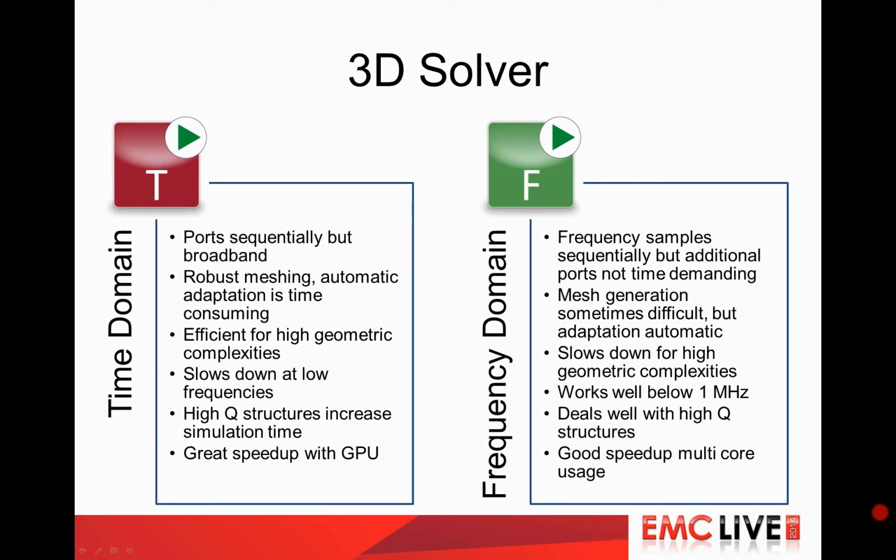For example, if you are designing a filter, say a multi-stage filter, this is something for which you would use the S-parameters. Then there is the frequency domain, or AC, small signal analysis, which gives you results in the frequency domain, voltages and currents typically in the frequency domain. And it has the possibility to apply the so-called combined results. This is something that I would like to explain on the next slides. Combined results is the way that the circuit simulation can access field results.